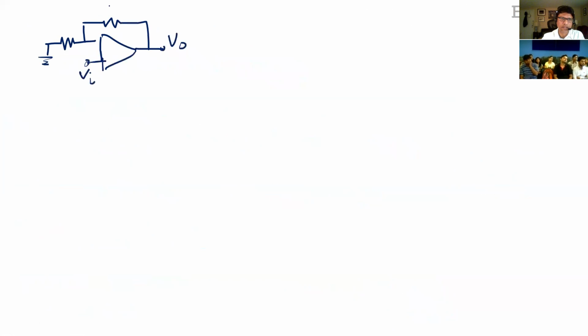So everyone is familiar with op-amp circuits. So you take an op-amp and let's say you wanted a gain of 10, and this is an inverting amplifier. So let's say this is your VI, that's your V out, and you ground this. So that's, let's say, a feedback resistor. That's your input resistor. So if you want V0 over VI, and this is an inverting amplifier, so I'll say minus 10. If you want minus 10, then you want RF over RI to be 10, right?